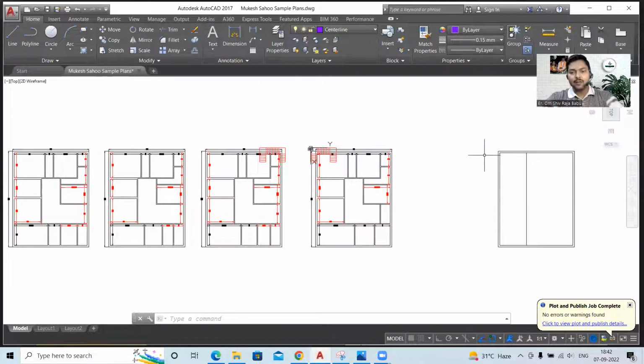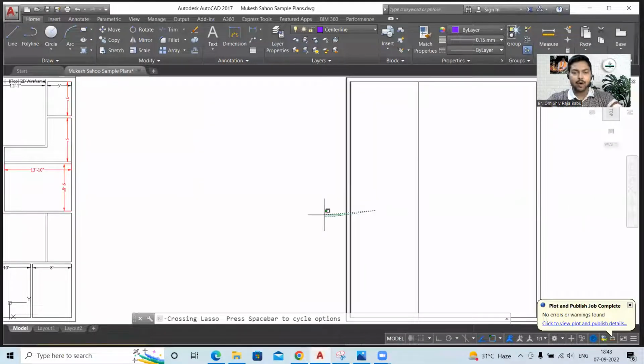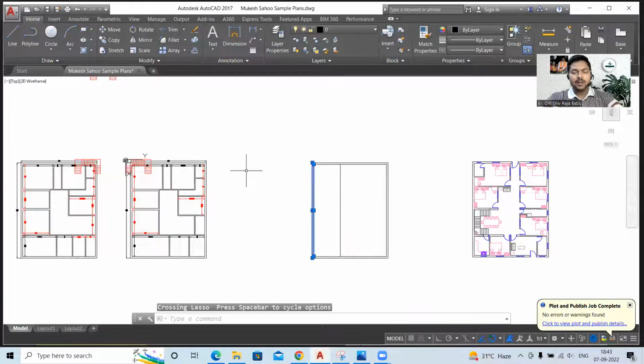So he had a 40 feet by 50 feet plot, an east facing plot. On the left hand side, that means on this side, the client had a blocked wall because he had another house already constructed here, so we cannot open any kind of window here. But on all the other three sides we can open windows because he had a space of 10 feet in the front. He doesn't need anything in particular for parking in this plot, so he will just park his vehicles in that 10 feet of space in front of the building on the east side.